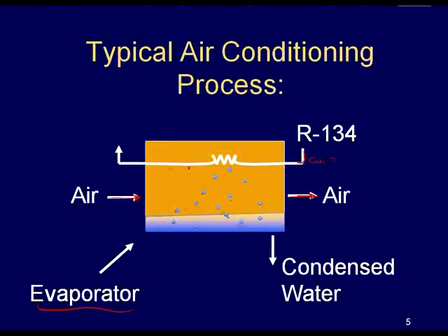Again, when you cool to a temperature at or below the dew point, liquid water will start to form, and then we have to take that out as condensed water. So if you park your car in the summer and go in, come back out, and drive away from a parking spot, you'll notice there's a liquid pool underneath it. That's from dew, or let's say condensate, that's formed in your evaporator and dripped out underneath the car. Not to be concerned.